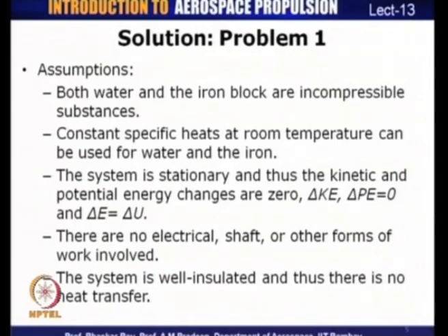Obviously, there are no other forms of energy interaction like electrical, shaft or other forms of work, and the system is well insulated, so there is no heat transfer between the system and the surroundings. These are some assumptions, some of them obvious and some of them not, and so it is important for us to state the assumptions if there are any.